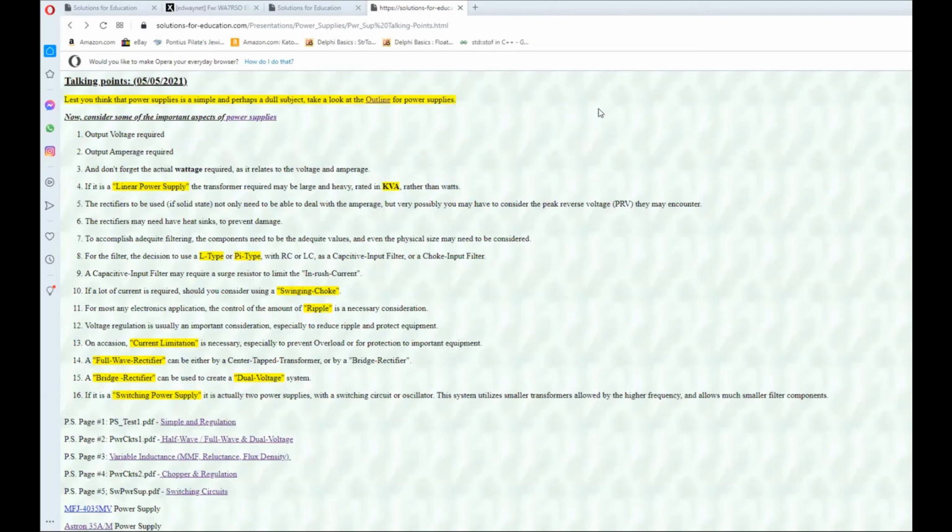At the higher frequencies, maybe I'll take a different approach to your question. The slugs were not solid iron. They were powdered iron in some kind of epoxy, as an example. The reason for that is that as you go up in frequency, the core starts absorbing too much.